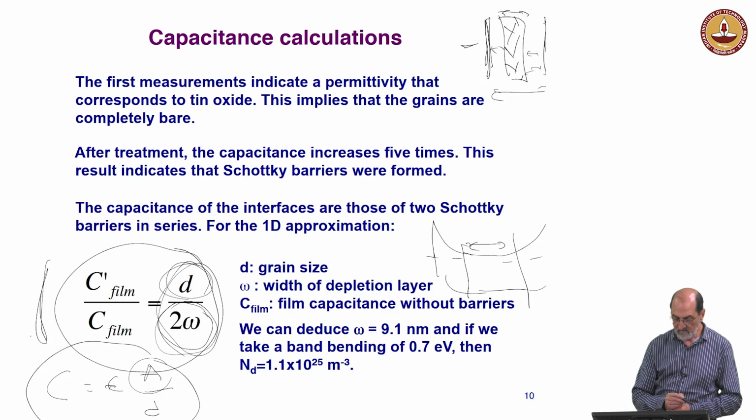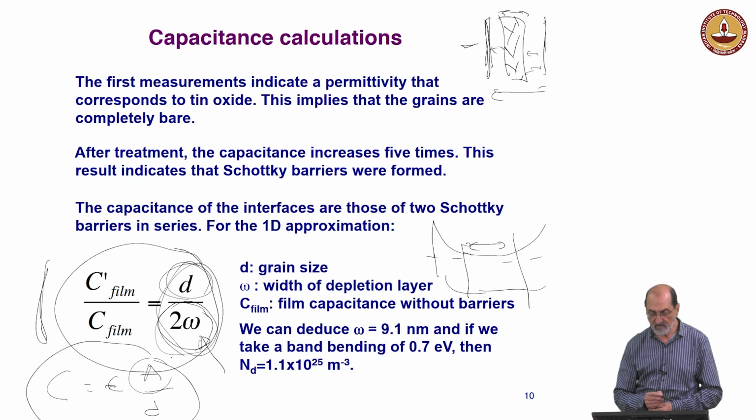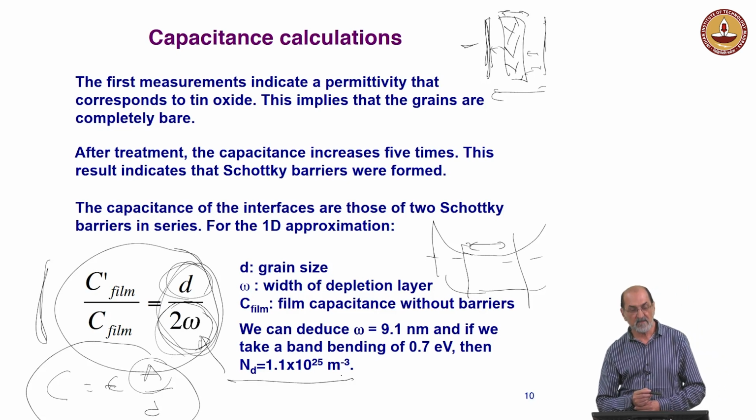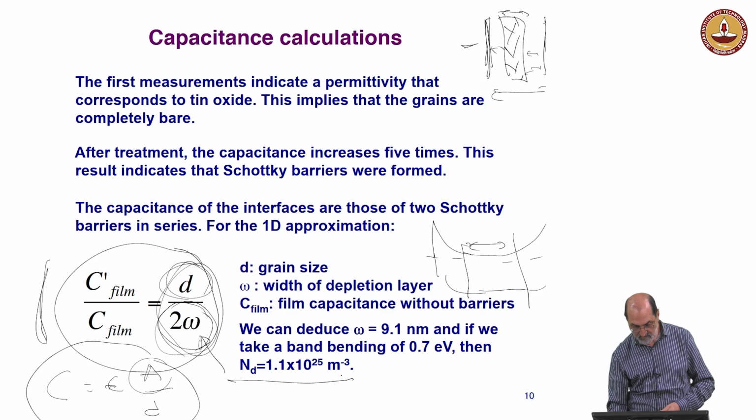And well, knowing all these things, we can calculate the width of the depletion region, and knowing that, we can deduce the density of oxygen vacancies. This is what we did, and it worked quite well.